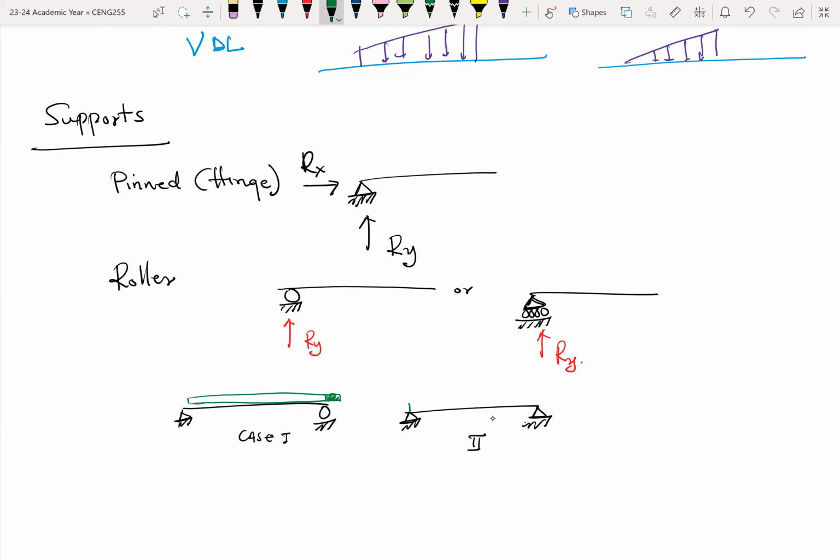Now, when you come to this structure, because both ends are pinned, when there's temperature changes, this end on the right, or whichever end it is, cannot elongate. And once it doesn't elongate, it means that we have stresses being built into the structure, or into the bridge. So it's like pressure. There's pressure on it. I mean, let me go with layman's terms. So it's like there's pressure on the structure.